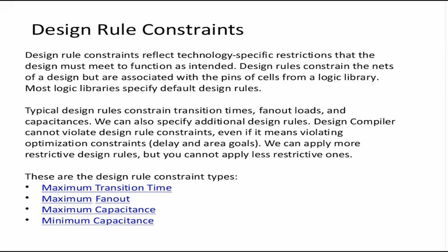So the constraint is on the net, but it is associated with the pins of the cell from the logic library. Most of the logic libraries have default design rules. You can open up the Synopsys 90 nanometer library and go to a particular cell. I showed in one of the library lectures the max cap attribute. Each output pin of each gate will have a max cap attribute. If the max cap attribute is not there, then the tool will take the default max cap attribute from the header.